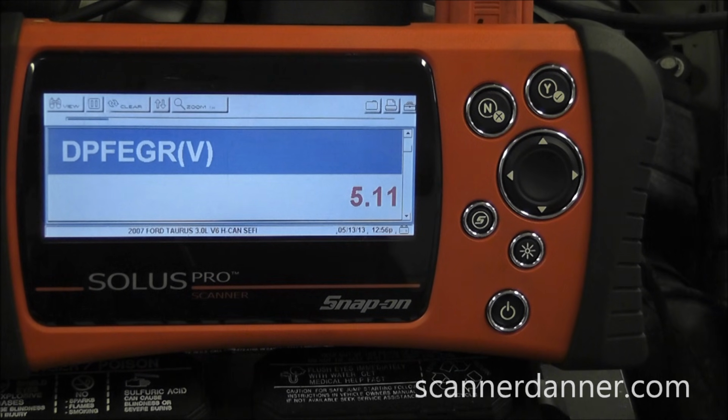34-page flowchart. Think about this. 34-page flowchart. T-pin in the control wire of the solenoid, knowing how to energize the EGR solenoid, and then knowing about a sensor circuit design with that 5-volt that we've talked about in other videos and I show in section 7. We're done. 2 tests. This needs a DPFE sensor, 100% certainty, no question about it.